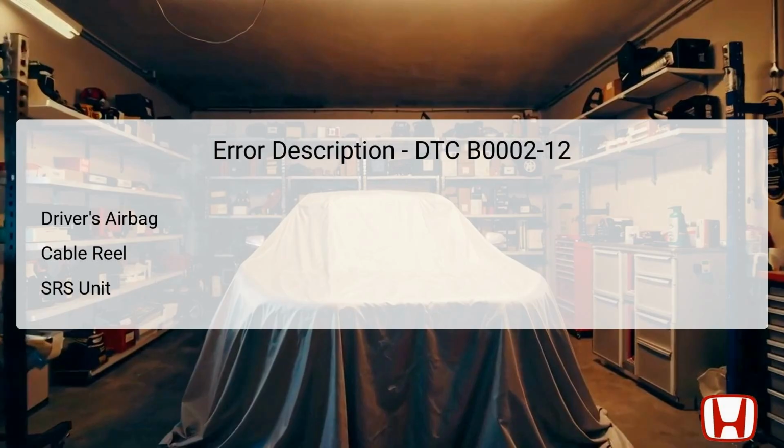DTC B0002-12 addresses an issue in the driver's airbag system, particularly involving the second inflator. The driver's airbag is a critical component of the SRS, designed to deploy in the event of a collision to mitigate occupant injury. The cable reel is another essential part, connecting several components of the airbag system and enabling its function during a crash. The SRS unit processes signals from these components and determines whether the airbag should deploy. If a voltage signal exceeds prescribed limits, the system identifies it as abnormal and stores the DTC.